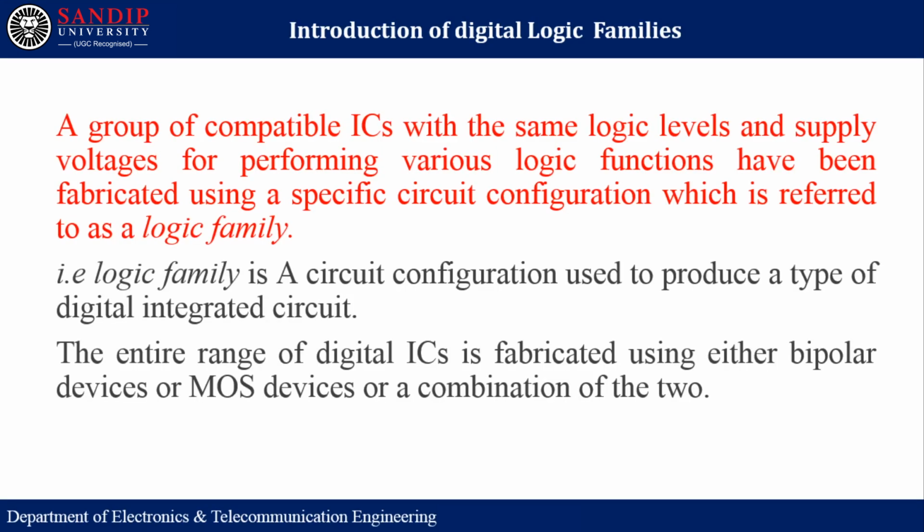Starting with the Introduction to Digital Logic Families: a group of compatible ICs with the same logic level and supply voltage for performing various logic functions, fabricated using a specific circuit configuration, is referred to as a logic family. That is, a logic family is a circuit configuration used to produce a type of digital integrated circuit. The entire range of digital ICs is fabricated using either bipolar devices or MOS devices or a combination of the two.